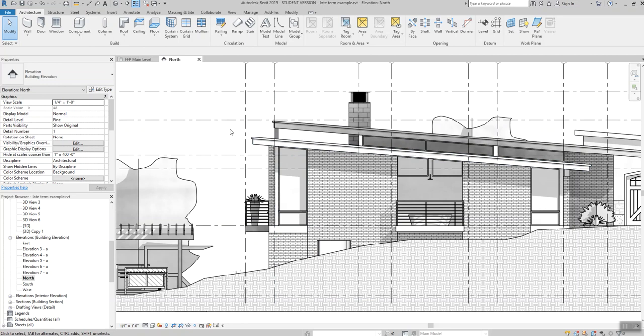You can use families for windows. Let me just say that, right? It's perfectly fine when you are working on a commercial or a residential project and you need to add just a basic square window, a round window, something not very fancy. You can use these pre-made families to add windows. It's great. But when you have anything out of the ordinary, we tend to think that storefront or curtain wall is probably the better choice for adding windows to a project, because of the ease of being able to make it a custom shape, okay?